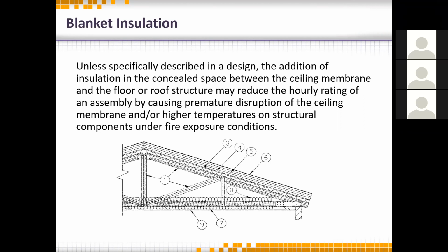The reason for that is if I test without insulation and we light up a fire in that room, the wall for sure gets hot pretty quick, but the ceiling is going to get hot a lot faster. And as the board calcinates, right, we saw it turning to steam in the video, that steam is allowed to go up into that attic space there and kind of dissipate. So it keeps the board cooler because that happens. But once I throw insulation on top of that, it's actually not going to allow that steam to go right through. It's going to keep it in the board, which means the temperature gets higher quicker, and we could prematurely fail the test.